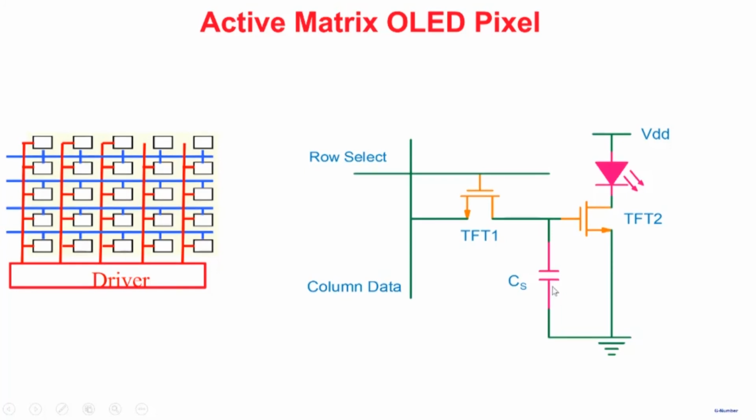Now you can see where the capacitor plays a central role, because once it is 150 candela per meter square here, that 150 candela has to be remembered, so that when you go to the next row and the third row and the fourth row, it remains on at 150 candela per meter square. If some other LED is 175 candela per meter square, well, that value has to be remembered, and the LED has to be on at that particular brightness level.